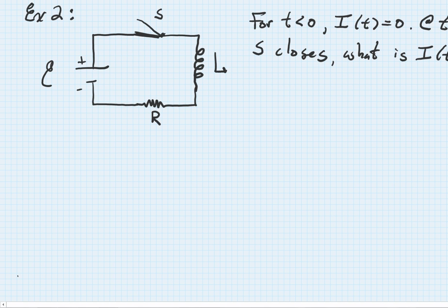Now, in terms of analyzing a circuit, as we've been taught, the F equals ma of circuit analysis are always Kirchhoff's laws. Now, the first Kirchhoff law, as we know, is the current law. And in this case, because I have everything wired in series, we know that whatever current flows out of this battery, which we're going to call I of t, that's really what we meant by the current flowing through the circuit.